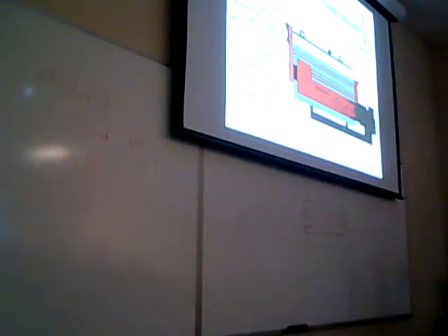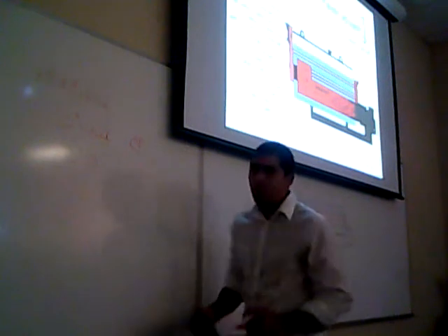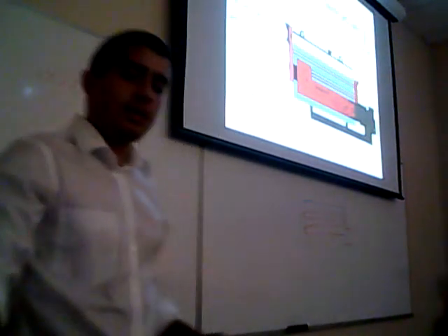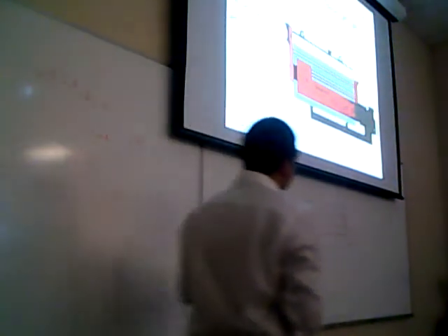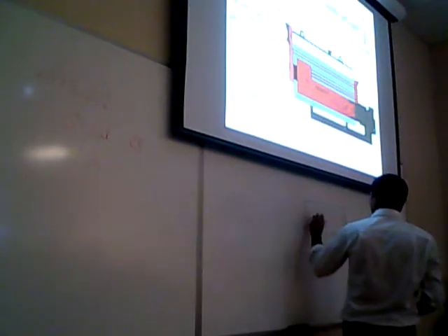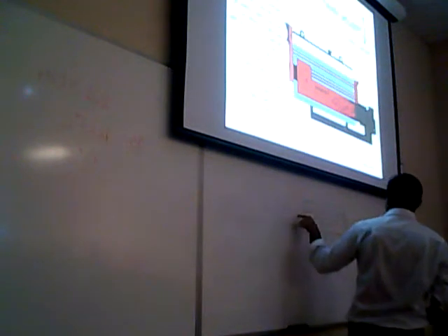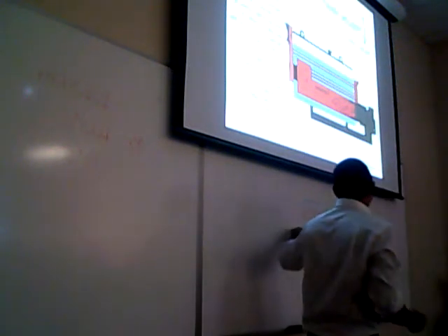The chambers in the combustion gas direction are called passes. So when you're going to buy or design a boiler, you want to know how many passes the boiler is going to have. What is the reason? In this case, you can see 4 passes, 4 times the pipe changes direction.